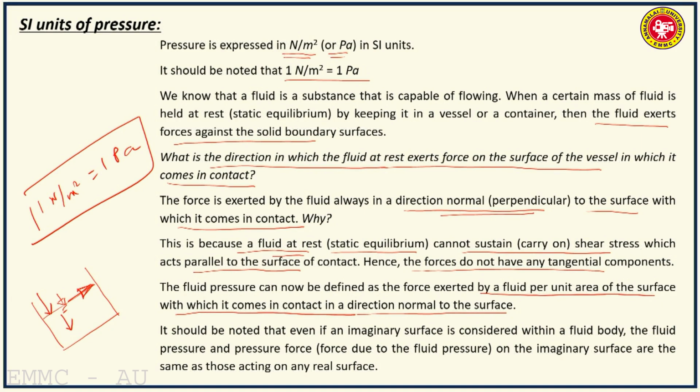It should be noted that even if you consider an imaginary surface within the fluid body, say for example like this, an imaginary surface in dotted lines, the fluid pressure and pressure force acting on the imaginary surface are also the same as those acting on any real surface.